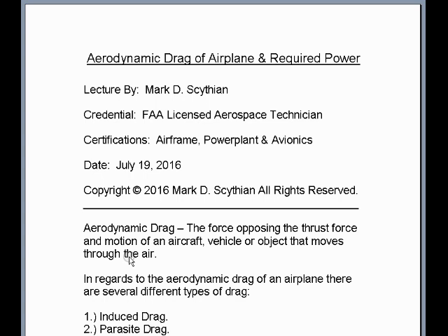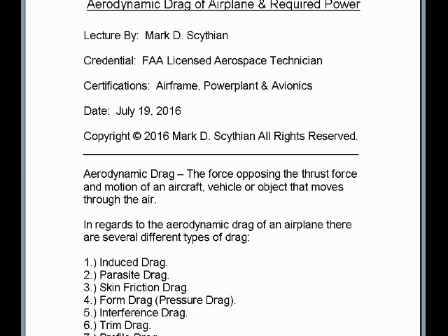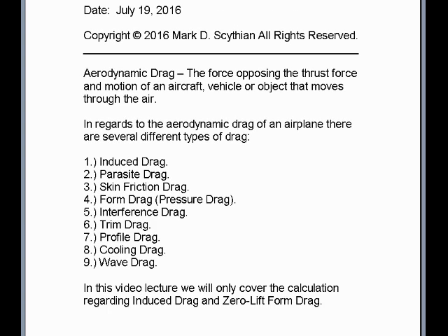moves through the air. In regards to the aerodynamic drag of an airplane, there are several different types of drag, including induced drag, parasite drag, skin friction drag, form drag, also known as pressure drag, interference drag, trim drag, profile drag, cooling drag, and wave drag. In this video lecture, we will only cover the calculation regarding induced drag and zero lift form drag.